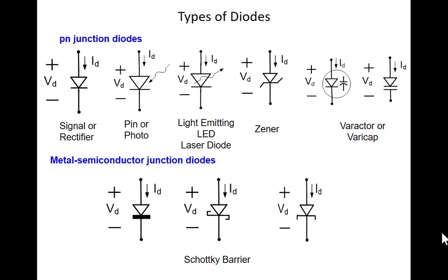It happens that they operate extremely fast. You can get pin diodes that operate in the gigahertz or tens of gigahertz range. So you shine a light in a fiber optic cable, and boom, somebody has the other end of that cable. You put a pin diode on, and you'll see the light on the other side. If you could toggle it at 5 gigabits per second, you've got a channel operating at a data rate of 5 gigabits per second. Make sense? Okay, so pin diodes or photodiodes are designed so that they intentionally respond to light. You shine light in at the junction.